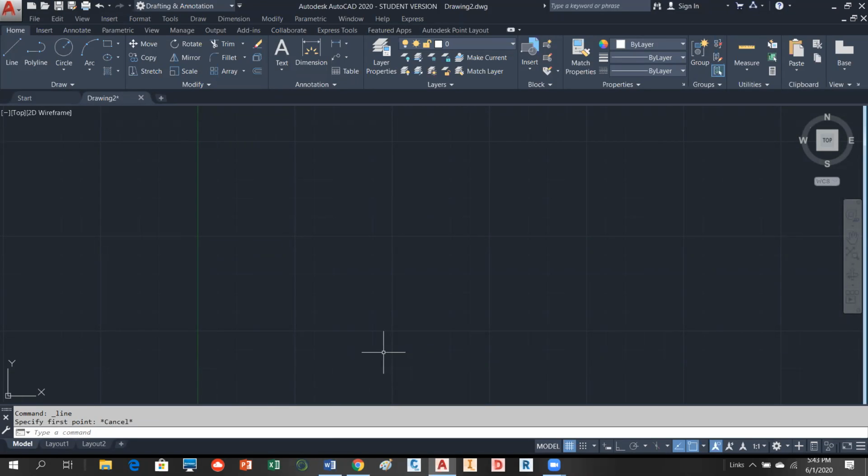Those have different functions. When you're dealing with a pointer, that's mostly a selection mode, okay? When you have the crosshair, you're basically in a drafting mode, and that only occurs when you're down here in the graphics screen. And when you come down here in the window or another type of box where you get the I-beam, it tells you that you can type, okay? So the pointer is selection, the crosshair is drafting, and this tool down here is typing, okay?